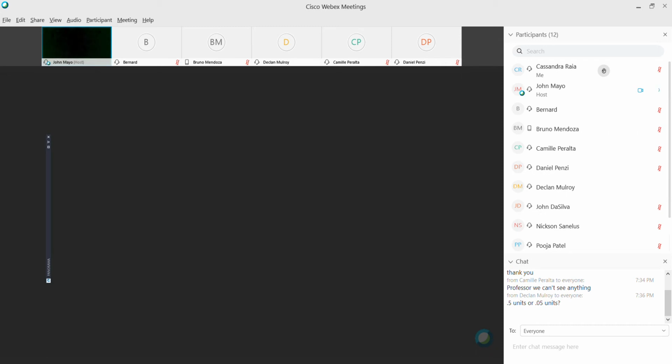Now I'm going to tell you, don't add the boundary until the end, because you're going to go through this surface and you're going to continually add more break lines. And if you go into your surface properties, the definitions tab, you see all the information that we've done. We've added break lines. We've added a boundary. If I now add more break lines, they're going to go underneath add boundary. And if I add break lines again, they keep going under add boundary. Not only is this a list of the things that's being done, but it's a hierarchy.